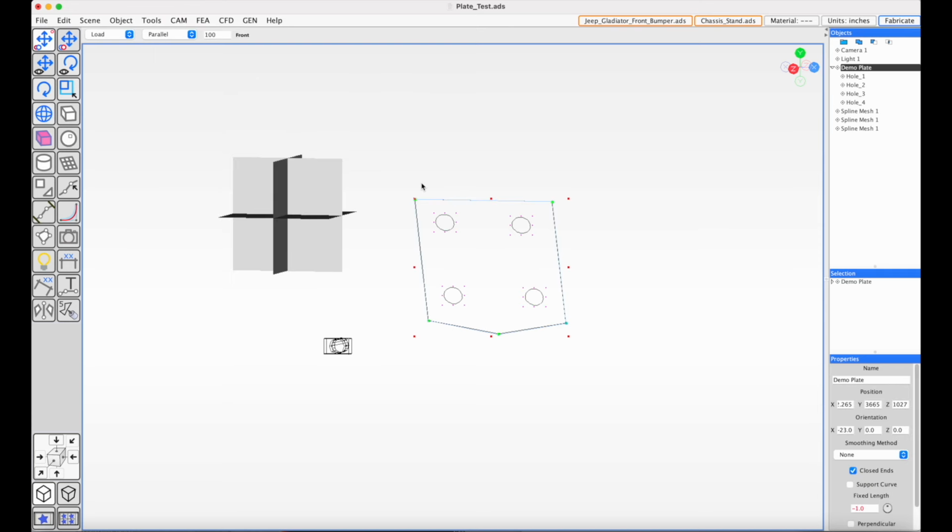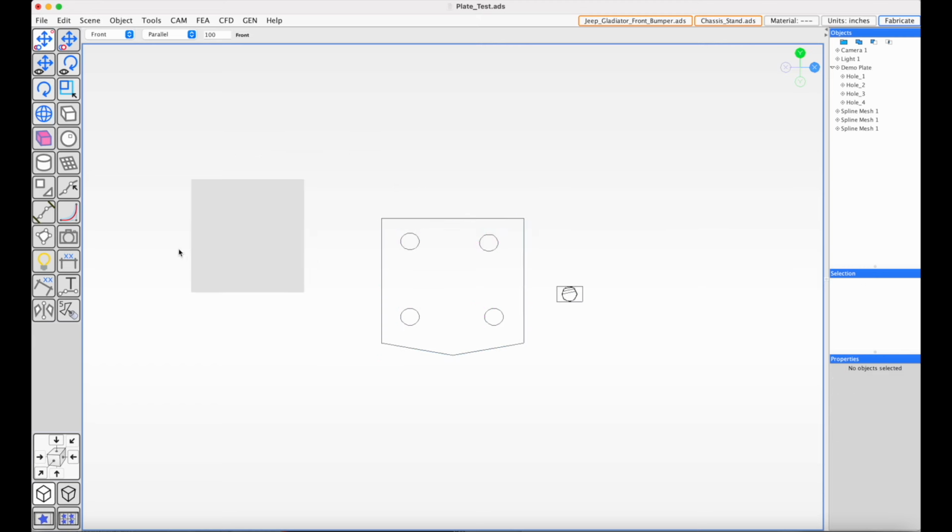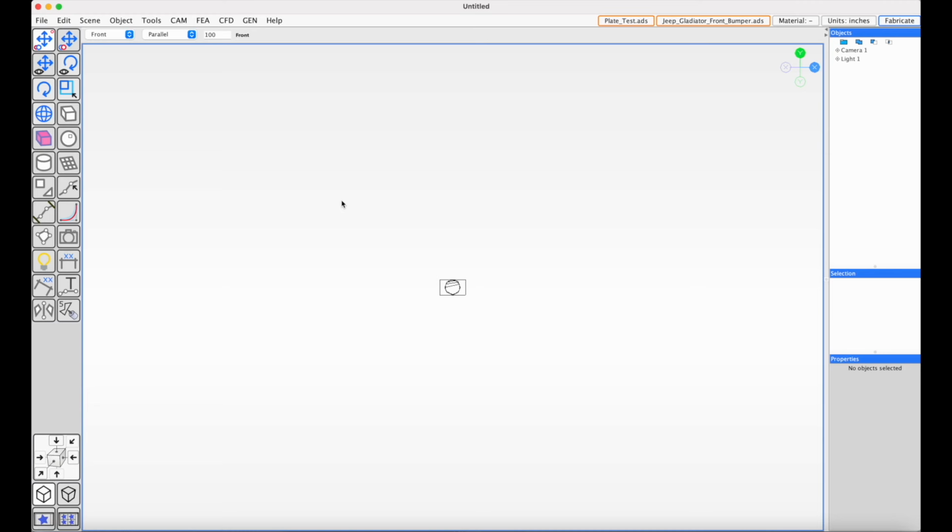Modeling with polygons is quick, but it's difficult to define distances. It's tedious to do that. So an alternative method is to import a 3D mesh object from another CAD application, or to use Boolean modeling tools to generate the cut profile based on the edges. Make a new project. So here is a demonstration of how to make a plate cut profile based on an object.